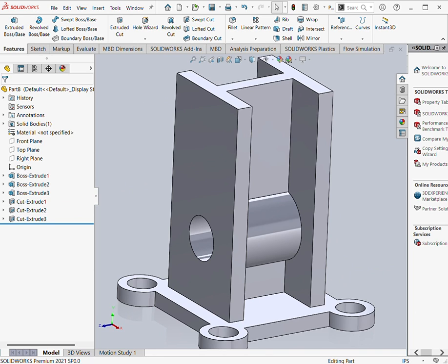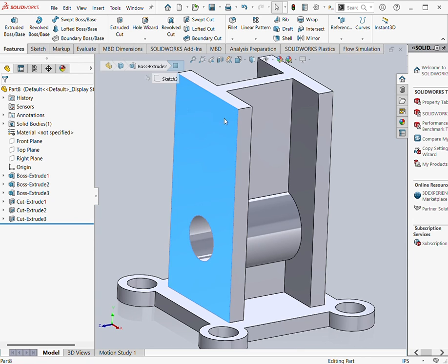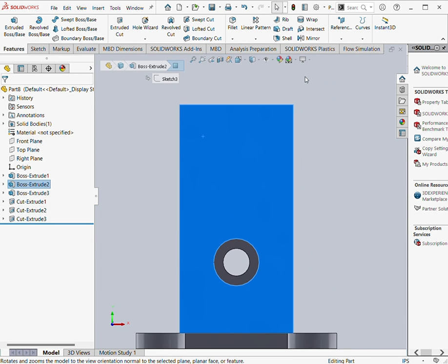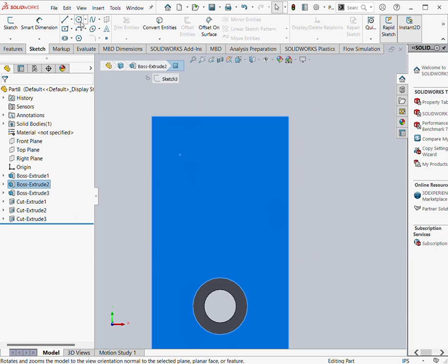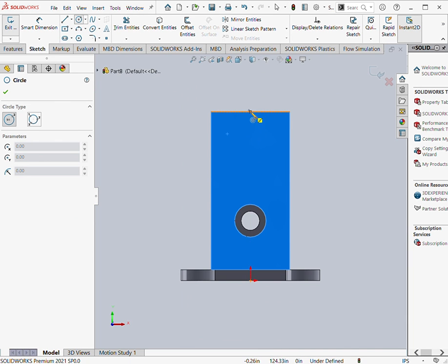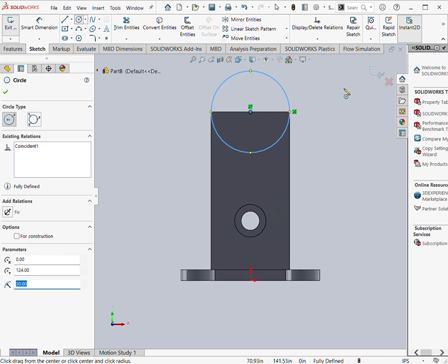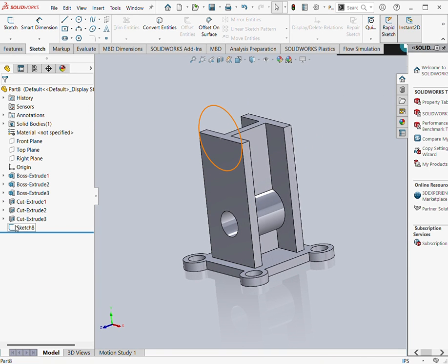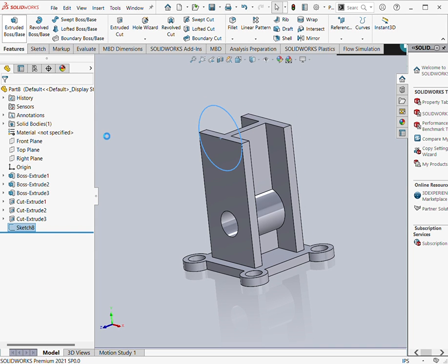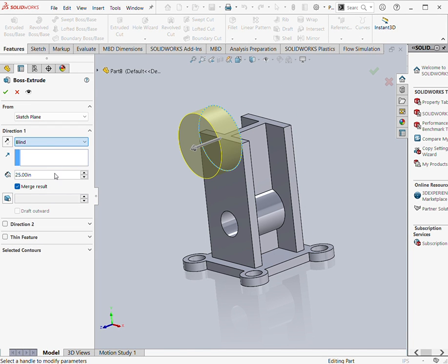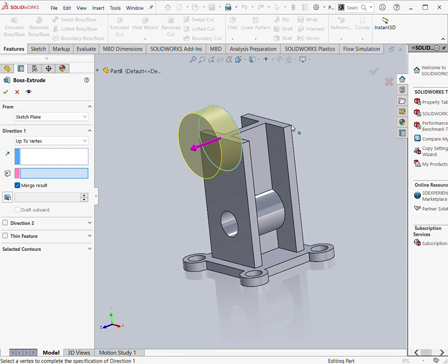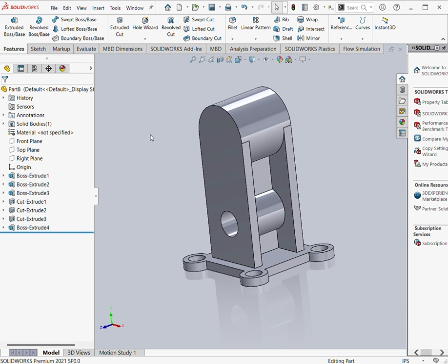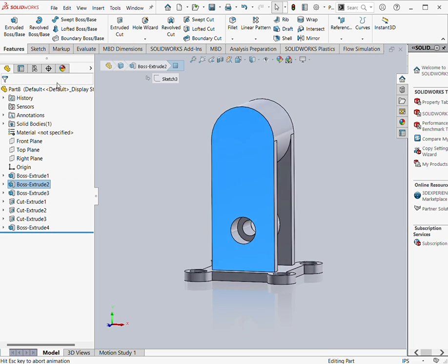Now the upper portion. Again you need some variable cutouts, but to make cutouts you need material. So first of all make a cylinder and then make cutouts. We go normal to this face. Here draw a circle and protrude it. So we choose this circle, sketch feature, extrude it up to the vertex, this one. You have this cylinder. Now you are able to make cutouts.